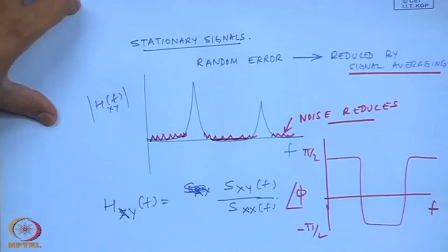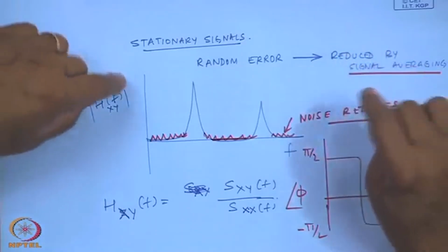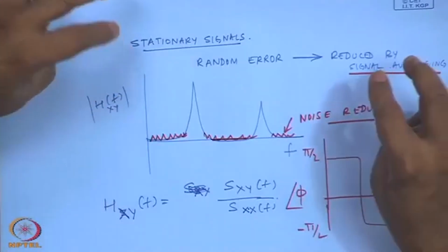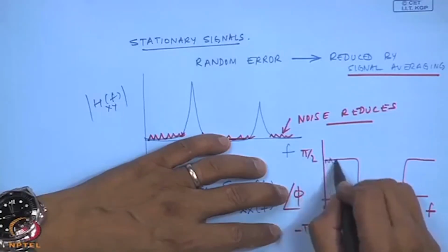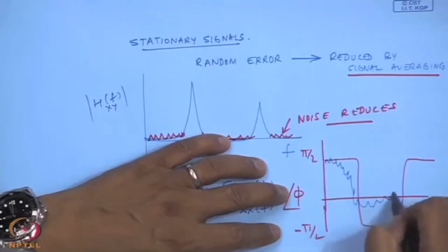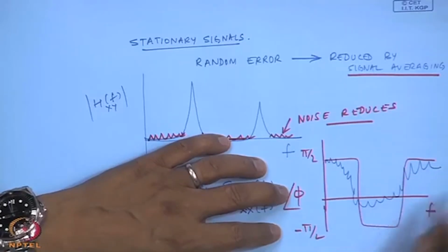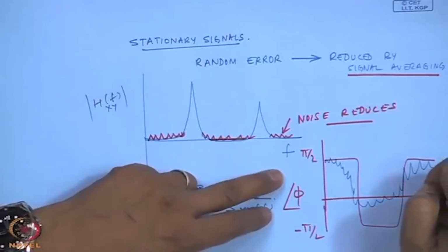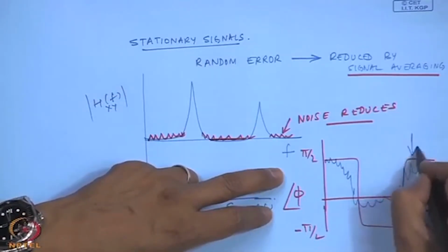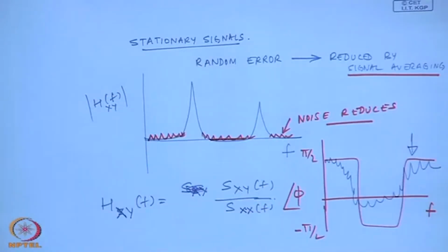However, when you do such analysis between two signals coming from a machine where there is a lot of looseness, you will see that this phase makes no sense, because if you do an average, you will not get any meaningful information, and that is what I mean by unstable phase between signals. So, these are clear indications that a system has looseness.